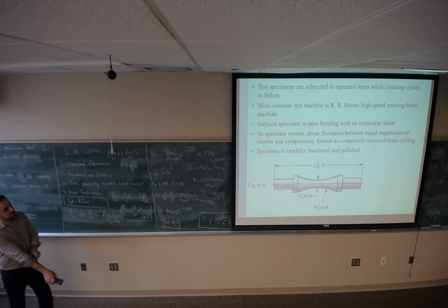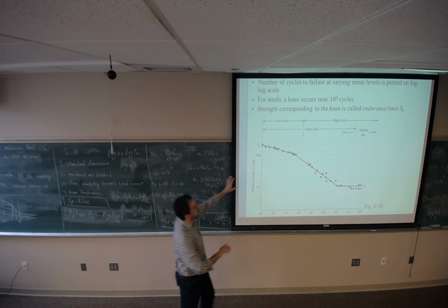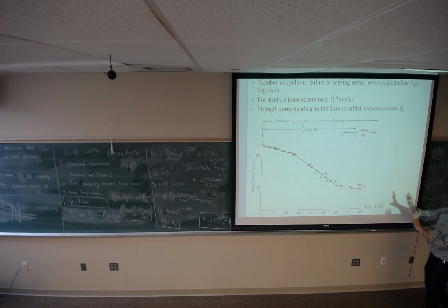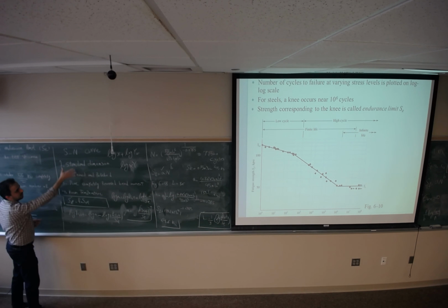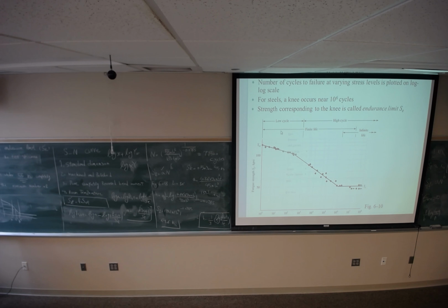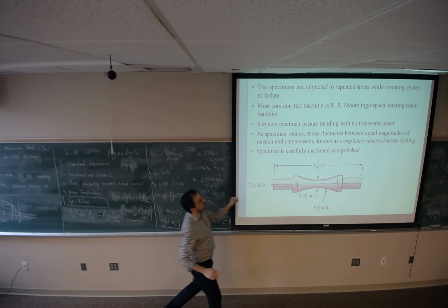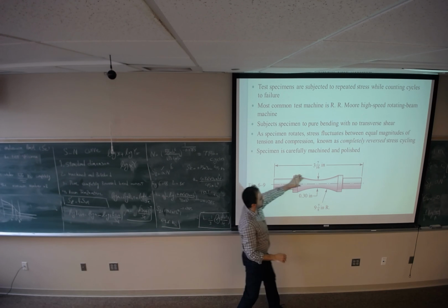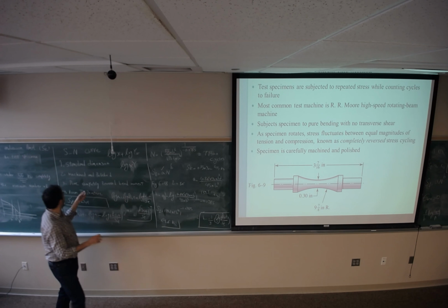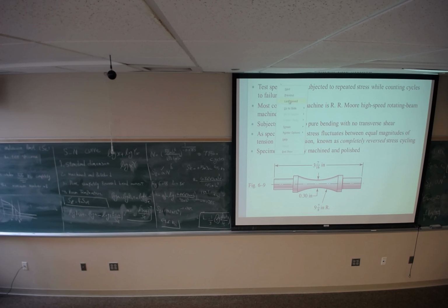All right. What you will see in textbooks or handbooks for different ferrous materials is the SN curve. This SN curve is based on these criteria. We should have a standard dimension. The surface should be machined and polished. We should have a completely reversed bending moment. It should work at room temperature. So these are the conditions that this graph is based on.